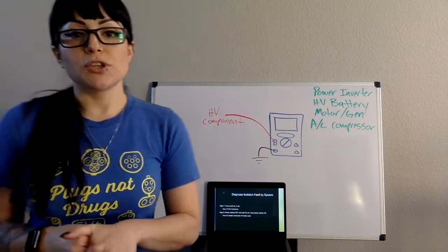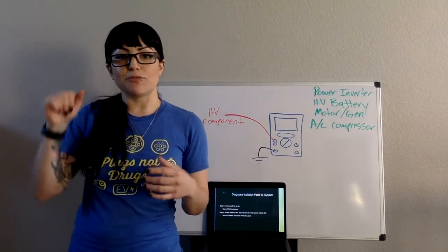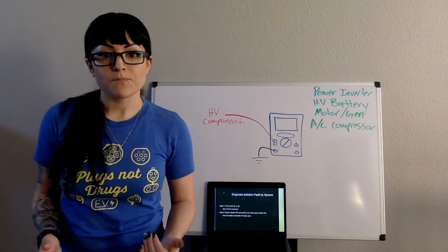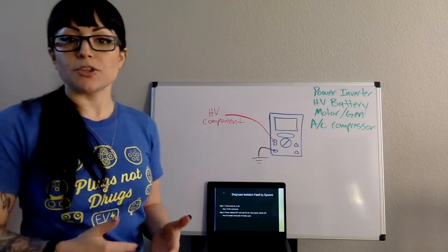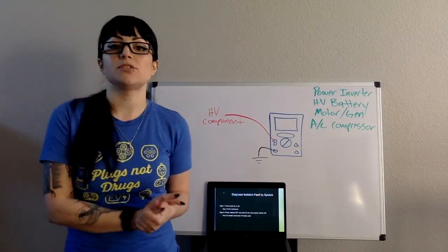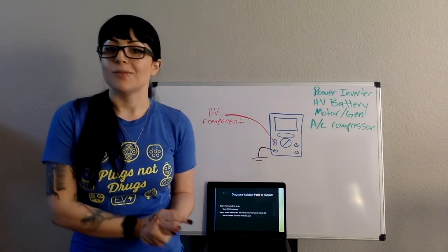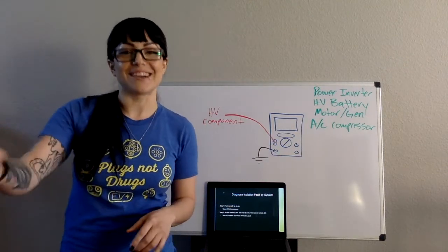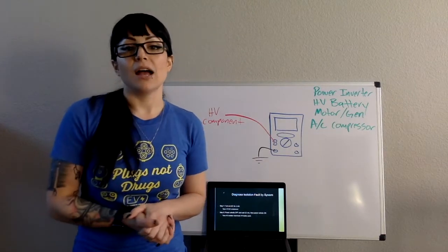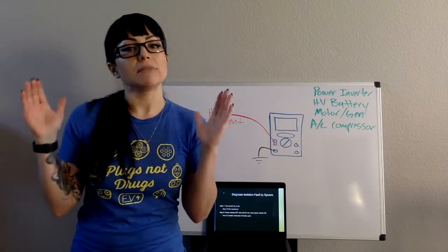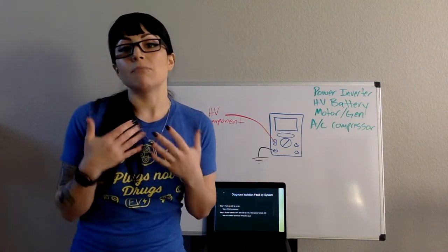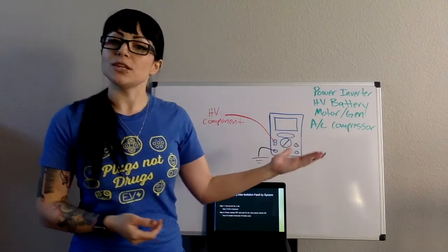Once you've gone down to step 7, so you've alternated drive and reverse, still no MIL, then what you're going to do is go to step 7. Step 7 is to isolate our AC compressor. Well, how do you think you turn on your AC compressor? You are going to turn on your air conditioning inside the cabin. So once you turn your air conditioning on, again, for about 2 minutes, we're searching for a MIL. If we get a MIL during this time, we know it's our high voltage AC compressor.